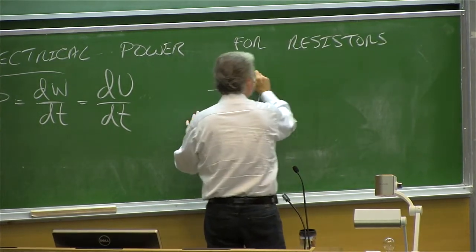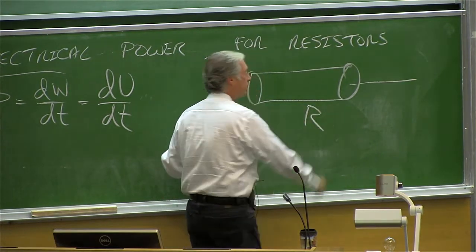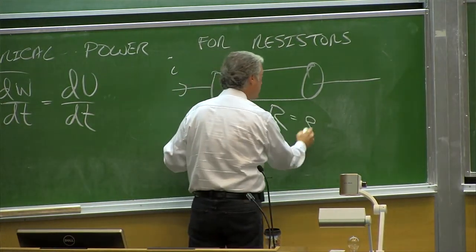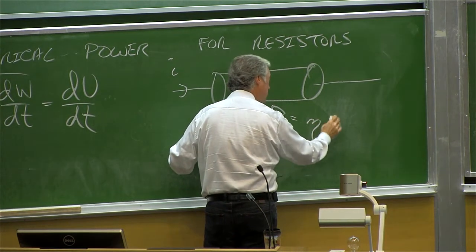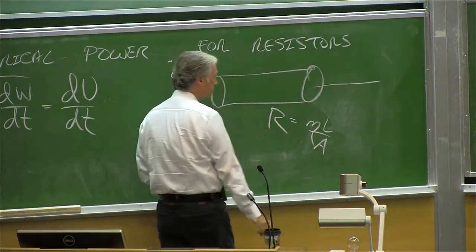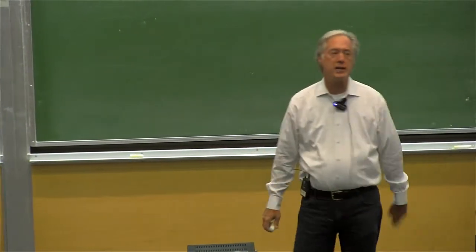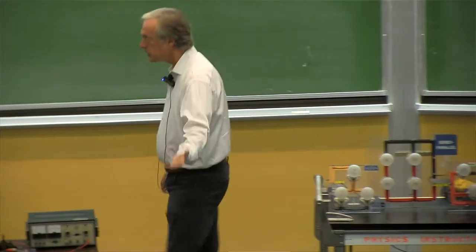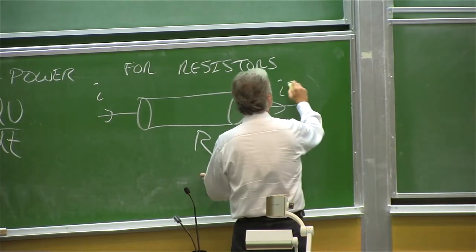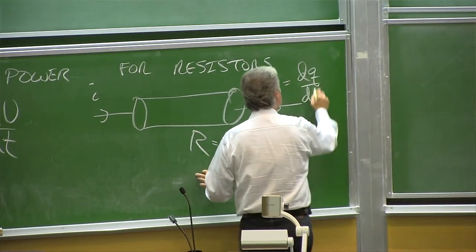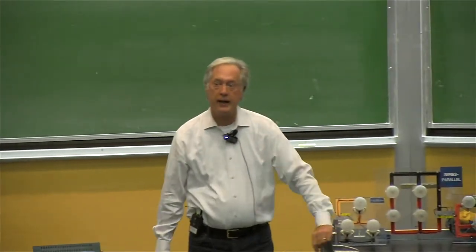what we're doing is putting a current into some resistor, and we think of it, remember, something like, what did we use for the symbol? Eta times the length divided by the area. So for the resistor, when we put some current into it, resistors do not store charge. So the charge that goes in one end is coming out the other, and the current that we're seeing here is dq dt, right? The rate at which the charge is flowing through that circuit.